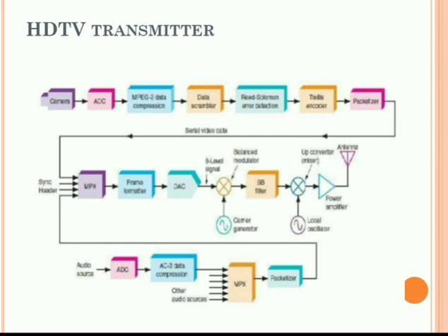Okay, whatever this particular trellis is encoding, whatever the data that was at the output of the Reed-Solomon error correction and detection, that was passed through the trellis encoder block. This particular trellis coding is not used in the cable television versions of HDTVs.